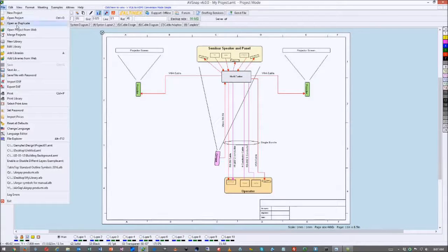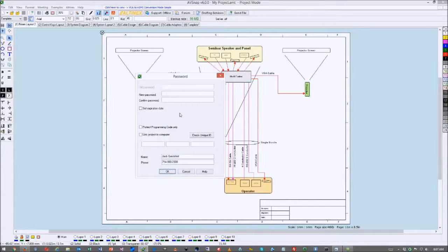Now you can also add additional functionality here. Let's go ahead and set the password, and you can say when you want the password or the file to expire. So if you set an expiration date, you can say 60 days from now the file will expire, and therefore it cannot even be opened. When you send something that's preliminary, you always want to put a 30 day expiration date. So in 30 days, you can send a new file. And then when you actually finish the last version and say, okay, that's a final release to the customer, to yourself, then you can release it without a password.